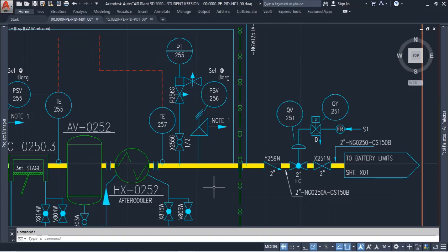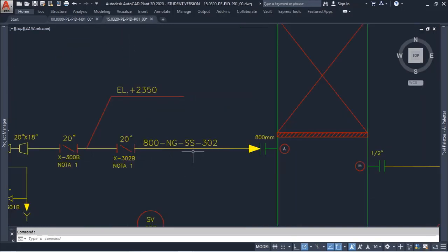It is very useful for safety issues, and as you have seen in the cooling system, I don't have that kind of information. So there is no wrong or right in the project, so there is no wrong or right in plant design, but you need to be alert to that kind of information in your documentation so that you can identify it, to know what is the pressure rating of this piping. You need to go to the line list.